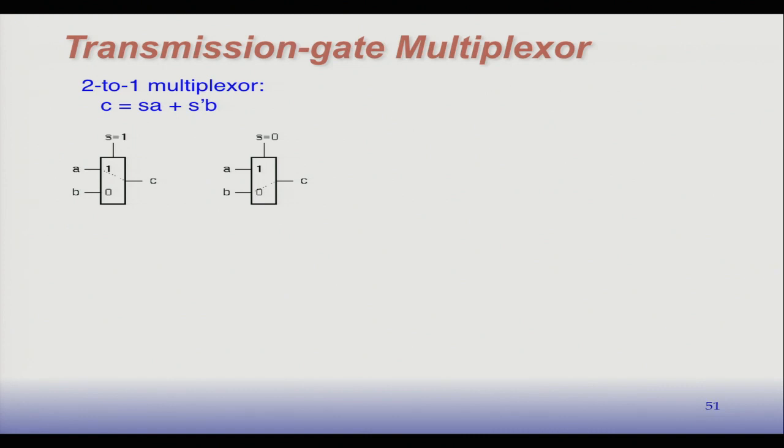And we know in CMOS we would probably not use AND-OR because that would be 6 transistors, and that'd be 6, and that would be 6. So chances are we'd just turn this into a NAND, make it a little more efficient, because we know NAND is equivalent to AND-OR. So we'd have an extra inverter here, plus 4 transistors, 4 transistors, 4 transistors, and that would give us a multiplexer. So far, everything I've told you this semester, this is as good as we could do.